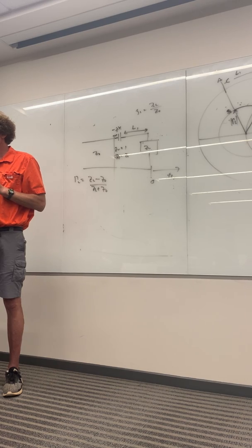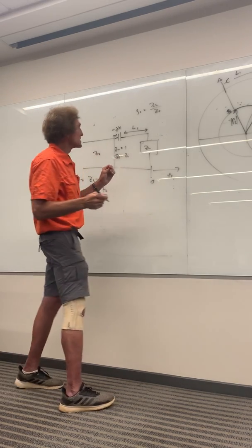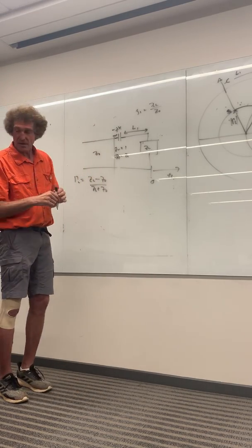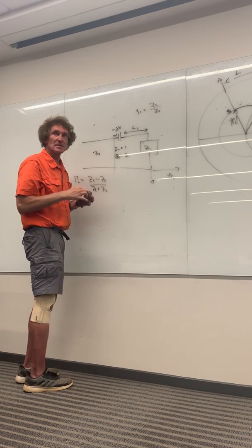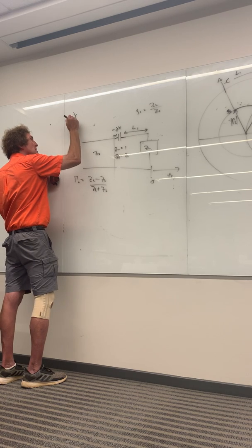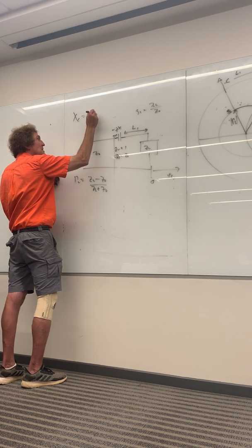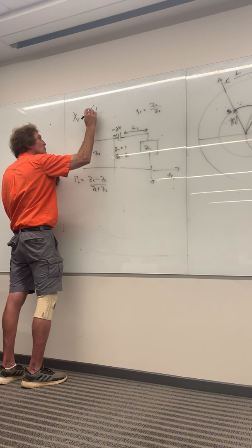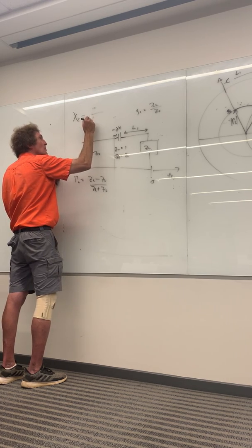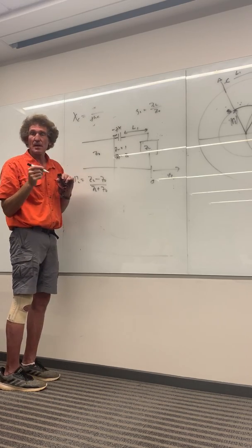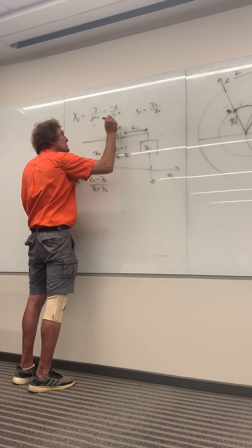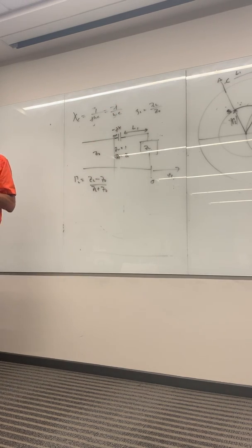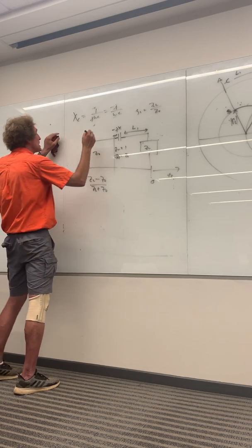Does everybody follow me on this? So let's go ahead and talk about this. Let me give you some real numbers. Better yet, we'll do it theoretically. So if I'm right here, and I want the normalized impedance of that capacitor to be minus jX, well, the actual impedance of the capacitor is what? Normally the way you were showing it was 1 over j omega C, correct, class? Well, that can also be written as minus j over omega C. Agreed? Now that's not normalized impedance yet. That's the impedance, correct? To normalize it, we would divide this by Z0.